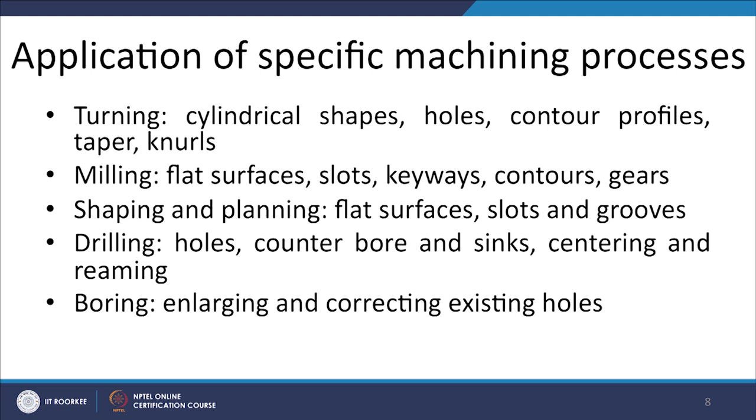And then drilling is used for making holes, counterboring, countersinking, centering and reaming. Drilling is the process which is used for creating the hole, and then counterboring helps to make a partial enlargement of the hole, and a partial conical hole is made in countersinking.